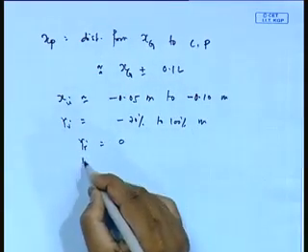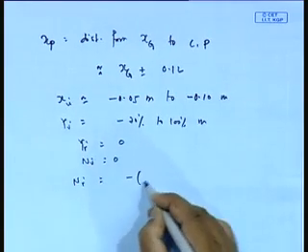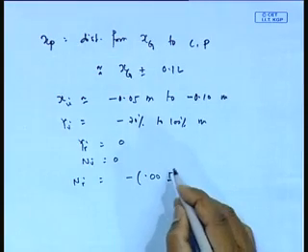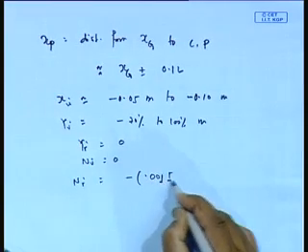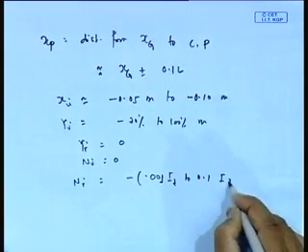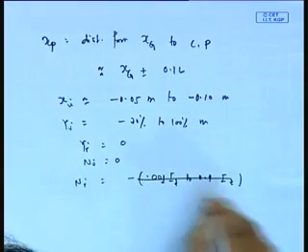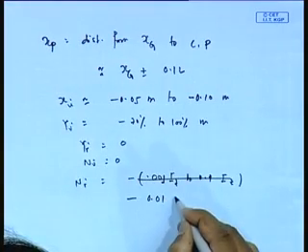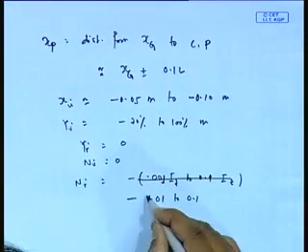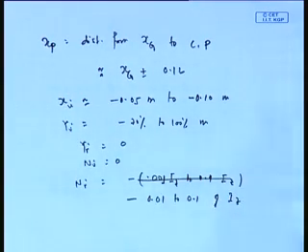Yr dot, Nv dot approximately 0, Nr dot equal to minus 0.01 Iz to 0.1 Iz. Of course, this is a wide variability, sorry, let me write it: minus 0.01 to 0.1 of rigid body inertia. Essentially, that is what it says.